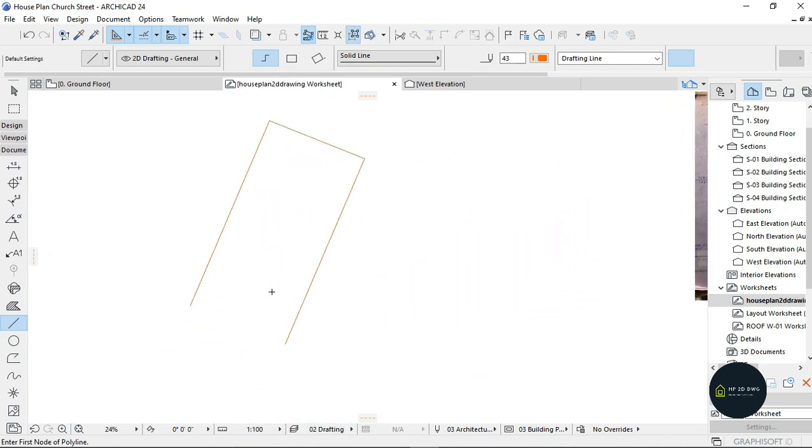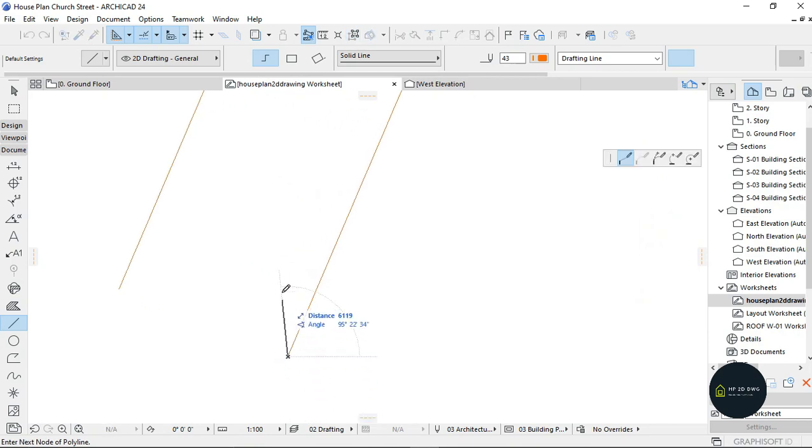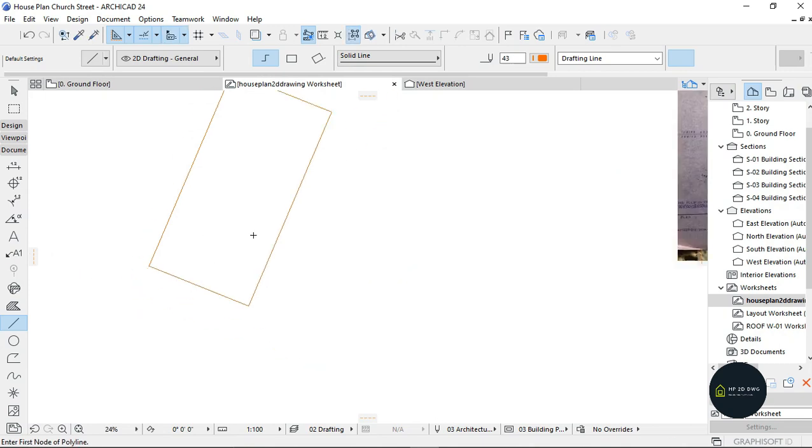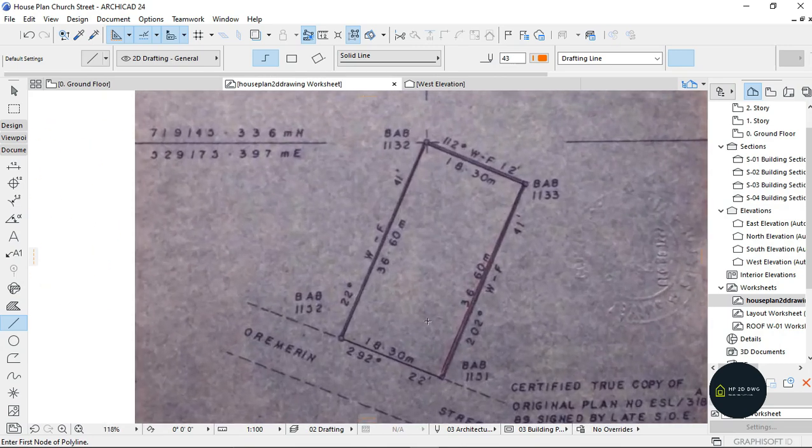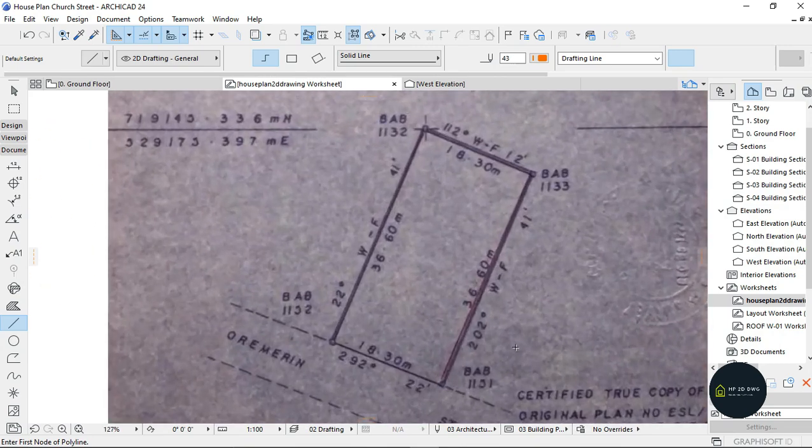Once that is done, you click on this line too, drag it up, make sure it's 90 degrees, and the degree here is, click on tab, the degree here is 292 degrees, click on spacebar, 22 minutes, and click on minus. Then you change your distance, which my distance here is 18300. Click enter twice. Then as you can see, it's giving me exactly this.